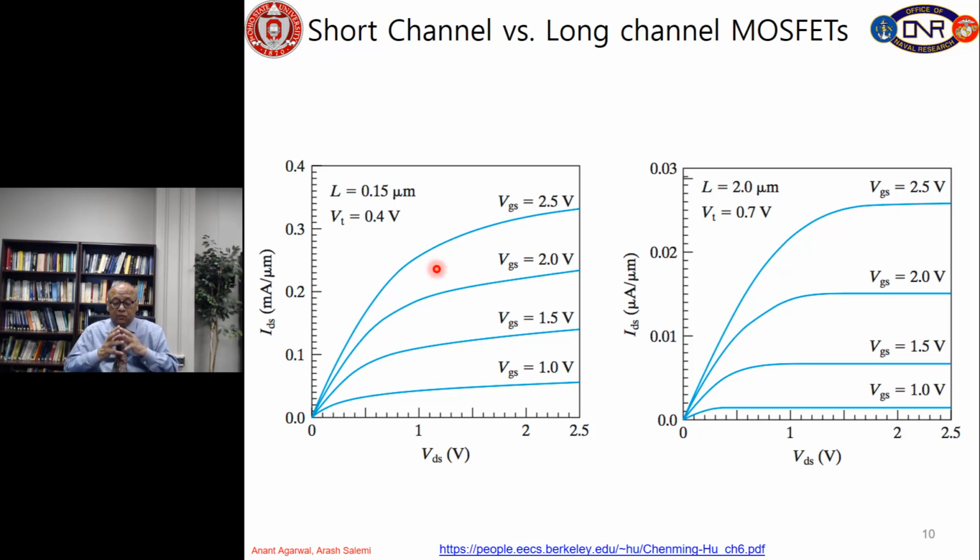So other than that, over the last 30-40 years, there has been a trend to decrease the channel length from 10 micron to today something very small, and the gate oxide thickness to about 50 to 100 angstroms. And then the gate voltages have been scaled from 10, 15 volts a long time, 30 years ago, to something like less than 1 volt today.